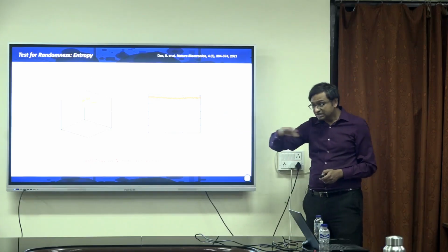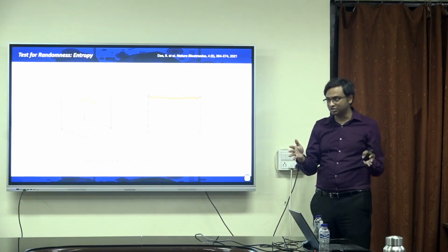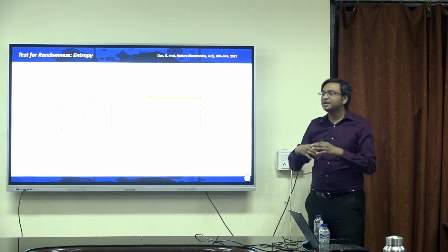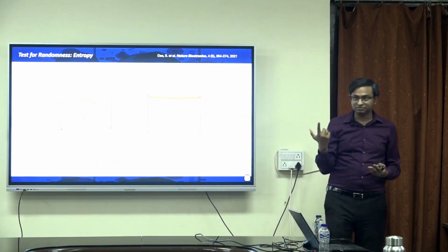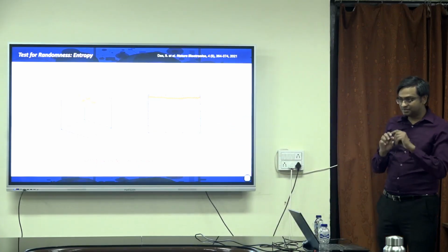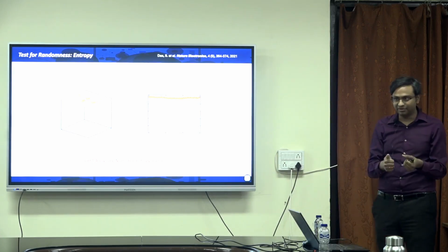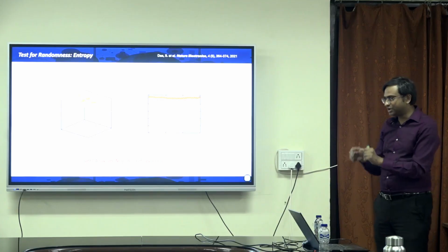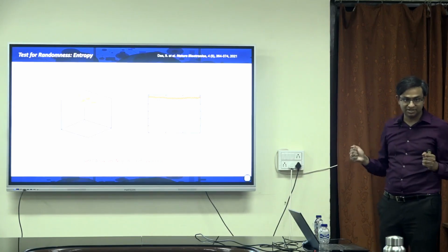So we found that these GFET arrays, for each GFET array we calculate the number of ones and zeros, and we found that the probability is nearly 0.5, so their entropy is close to 1. Okay, that means that GFET array works. This is something you have to test. You cannot just claim anything to be a PUF. So these are the tests you have to do and show your reviewers that you have done all these tests and now you can claim that this is a physically unclonable function.